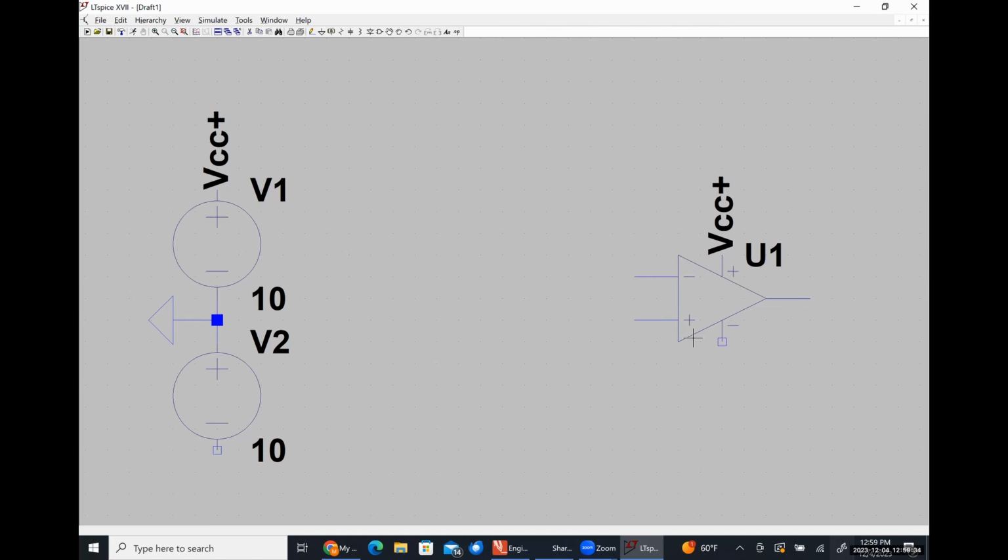So instead of physically connecting these 2 points with wires, I'm now telling this point to reference this voltage so that I get a cleaner schematic diagram over here in order to analyze and implement and all of that kind of good stuff. I'm going to do the same thing with VCC minus. So I'm defining it here, and then I'm referencing it over here. So now my supply voltages are set up. I'm going to create two more voltage sources.